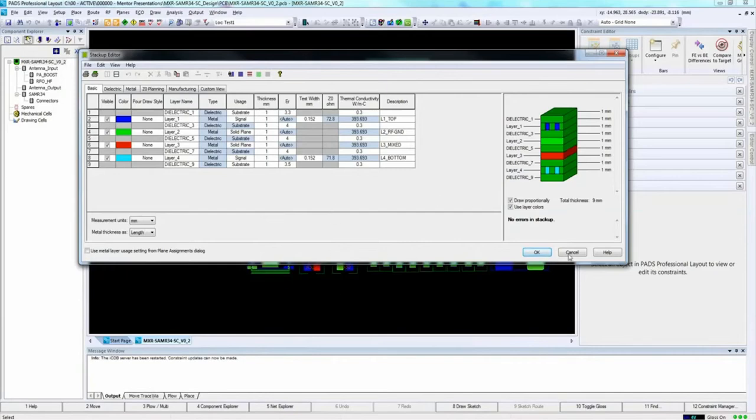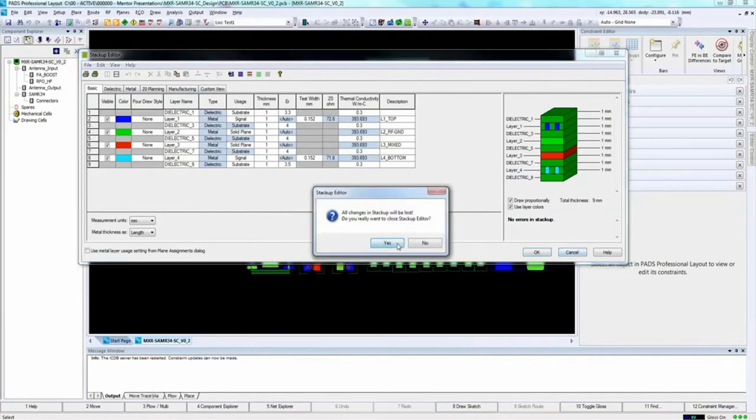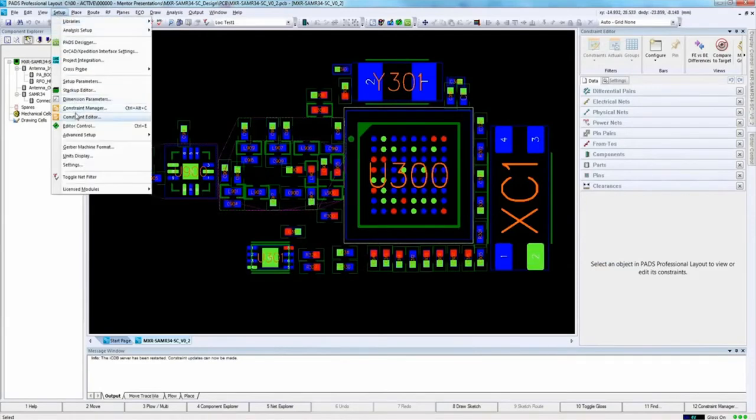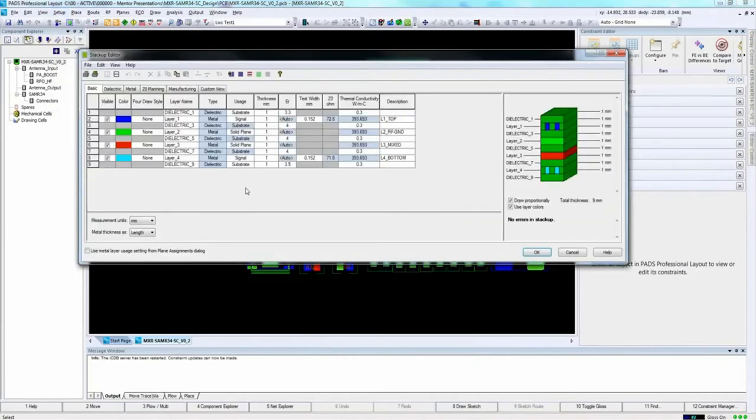And we looked at that right here, where we had different groups of components. So our board stack-ups are a really good place to start, and it's necessary in high-speed designs to have at least one complete ground plane, like we have right here on layer 2. So we also want to remember to use microstrip traces for sensitive signals.